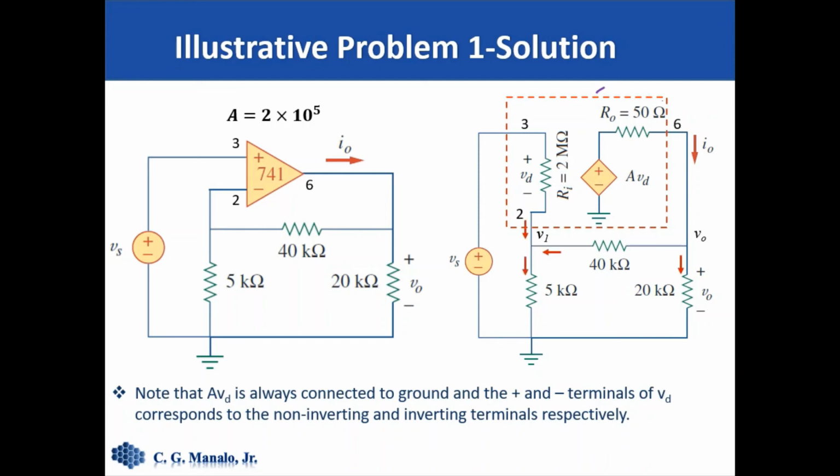So to solve this using nodal analysis, first we identify the nodes that we will use to create KCL equations. So here, these are the nodes V sub 1 and V sub naught. I've also indicated the direction of the branch currents towards or away from the nodes.